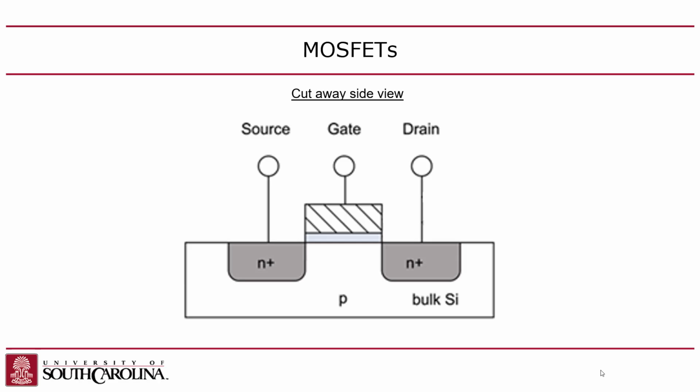And so it'll have an on resistance, which is ideally as low as possible, right? And then if the gate doesn't have a voltage on it above the threshold, then the transistor's off, in which case you have the off resistance, which is very, very high. As high as possible, because the higher that off resistance is, the lower your leakage current is, right? Make sense? Okay, so that's the way they work.